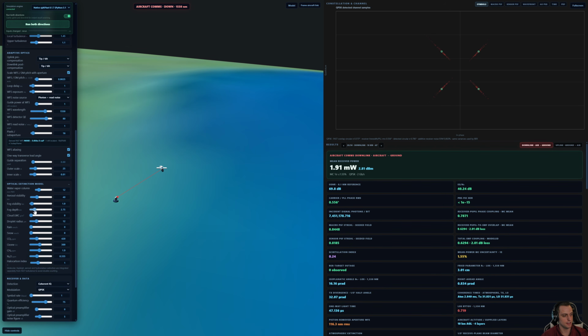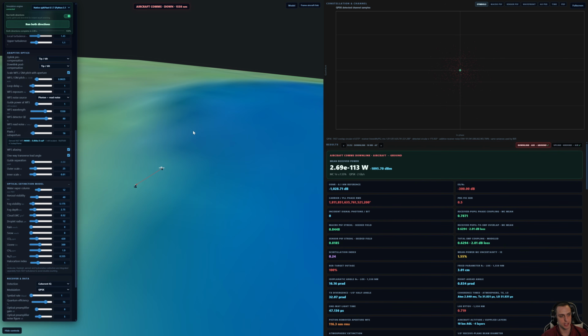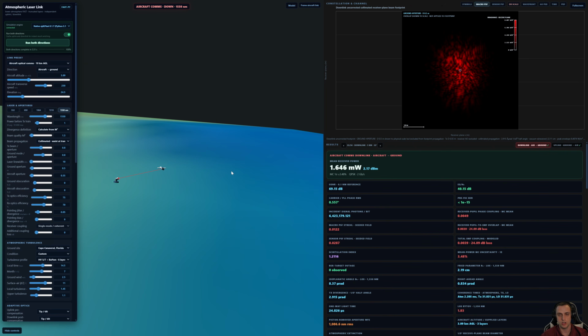We've already talked about this, but if you had any clouds at all, then your link budget is going to be destroyed no matter what. We have minus 1,000 decibels getting through the clouds here. And so it's just impossible. And I didn't show that, but the same is true for pointing down from space to Earth, and 70% of the Earth has clouds.